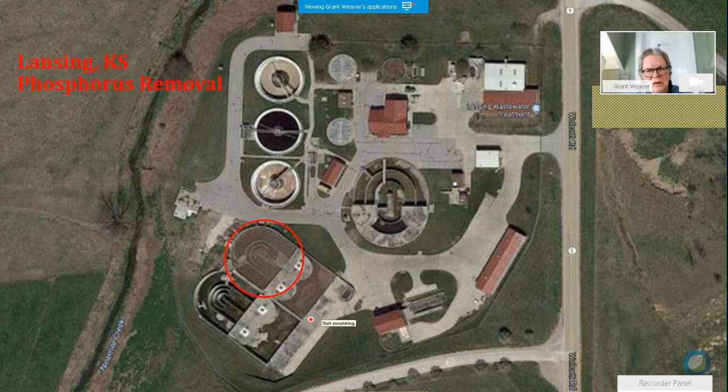So minus 200. The anoxic zone, I like to see that more in the minus 100. Now that's going to be constantly refreshed with high DO water coming out of that circle, out of the main ditch, coming in here, moving through. So there's always going to be a lot of DO coming in here. So this one we're going to try to get minus 100.